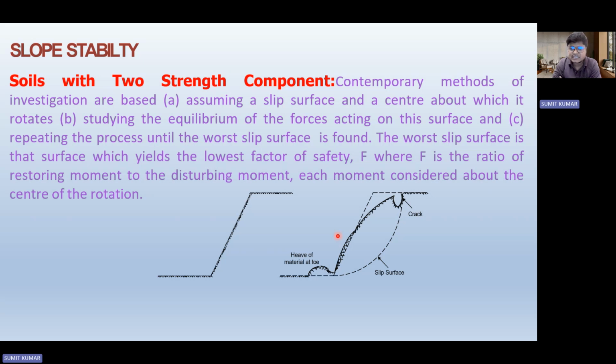Like we are using the strength reduction method, which is based on finite element assumptions, in which we use iterative methods, like the Newton Raphson method or many more things. So those are also things which come across these days in finding the slope stability for specific sites.